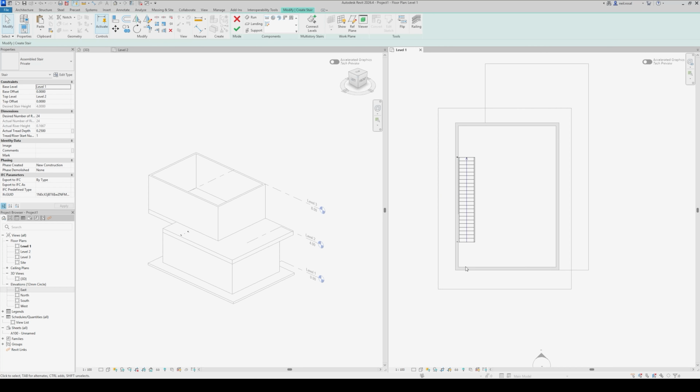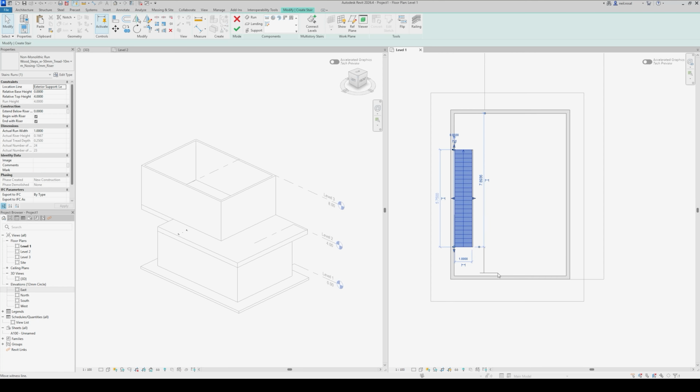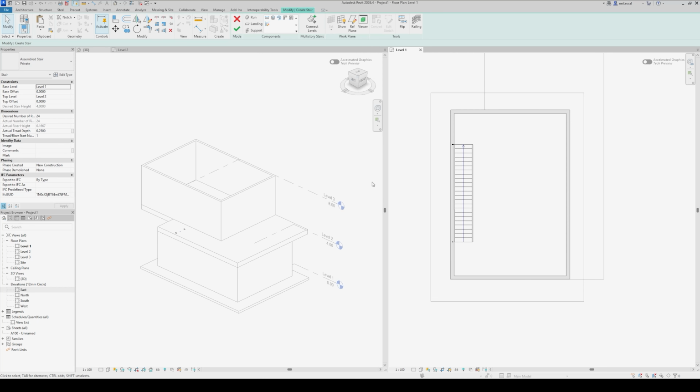If I want to have one offset, it'll automatically connect between levels. I think that's what's so brilliant about Revit. It's so quick and easy. But also you can change the dimensions of your stairs, like its step level and its riser height, but its riser height is also fixed to the levels of your project. So you've got to be wary of that. And it's dependent on your number of risers, so be wary of that as well. I'm not going to change anything to the levels. It's automatically connected. And I'm just going to move my stairs to a better and fixed offset, like 2 meters. And that's practically it for the stairs.